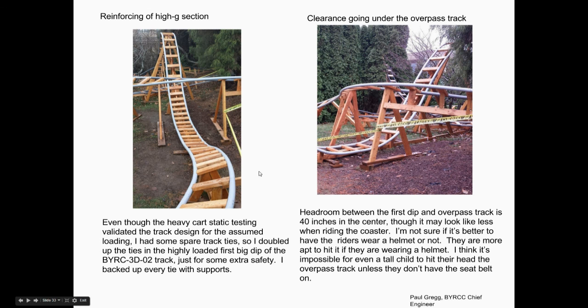I modified this track a second time. Well, I was doing it a third time. When I was modifying it a second time, I tried to just crank it down and screw it down and then apply a blowtorch to the sides and heat it up so it would kind of relieve the stresses and bend. But anytime you put a torch on something, you're going to heat one portion more than the other, and all the bending happens at that spot. So I redid this whole front section of track, and it turned out a lot smoother.